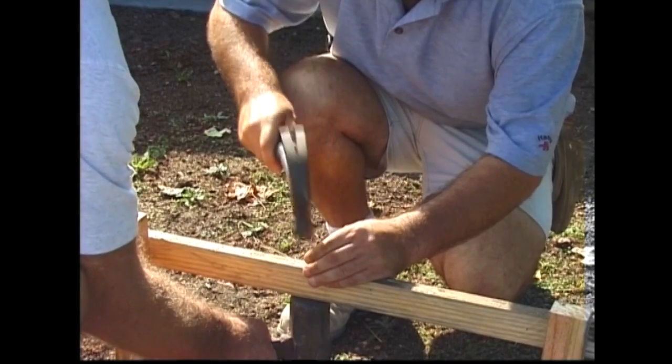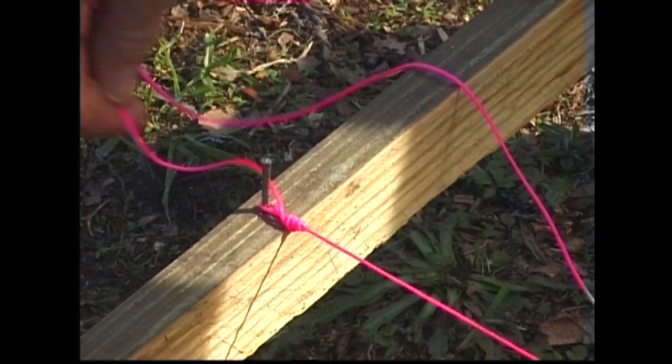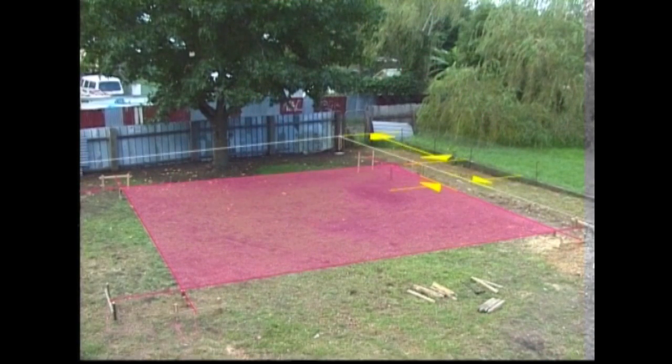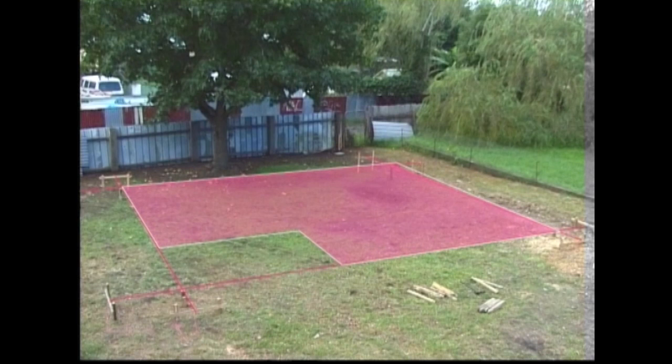Because all ledges have been levelled to the same height, the 4 string lines accurately set out the perimeter dimensions of the building correctly located on the site with the required setbacks. Not all buildings, however, are rectangular in shape. In setting out L-shaped or T-shaped buildings, the first step is to peg out the overall rectangular envelope that contains the building.